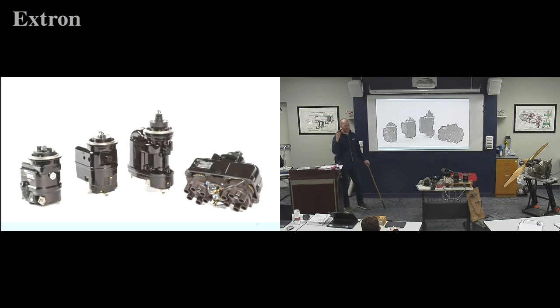As far as the contacts that are opening and closing, the capacitors, the little distributor finger that's going around, you've got two sets of all the components that would typically go bad. So all the stuff that would typically go bad, you have two sets of. So they kind of covered it. Aviation's all about weight, and theoretically that one weighs less. So we'll go with it. But it's pretty uncommon for the reason you said, and those things are expensive. And they're kind of heavy, hanging off the back of the flange. There are some issues there too. So you don't see these very often.